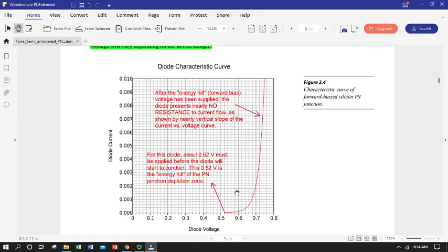So that is how the diode acts in a circuit with respect to how much voltage is dropped across it. This is its current-voltage relationship. So it's very different than a resistor, which is just voltage equals its own resistance times current flowing through. In this case, the current is going to be this exponential function of applied voltage, and only in the forward direction.